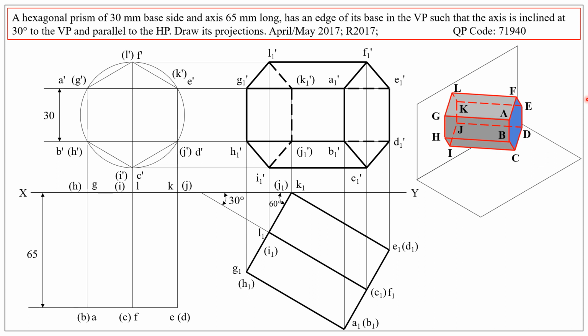So this is the final front view. So in your drawing sheet, you need to draw this, reorient the top view like this, and obtain the final front view. Of course, we need to give all the dimensions, name all the corner points, give the specified angles. Thank you.